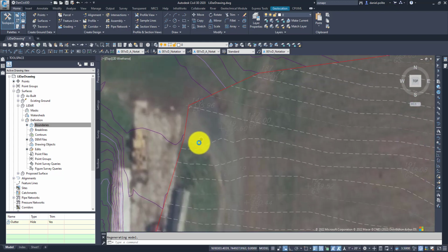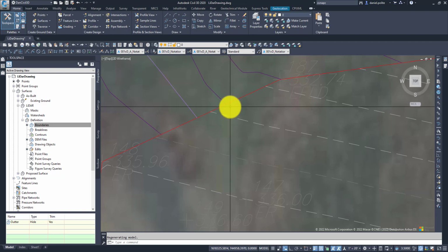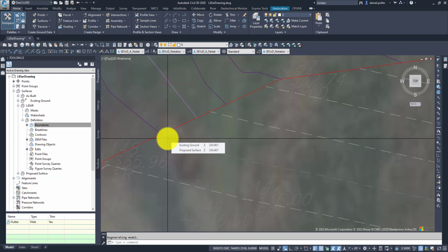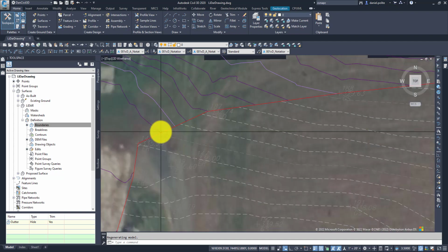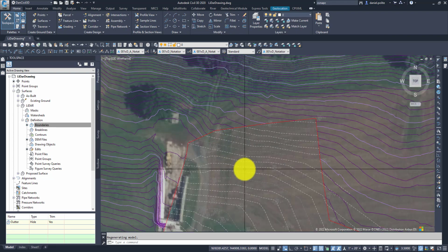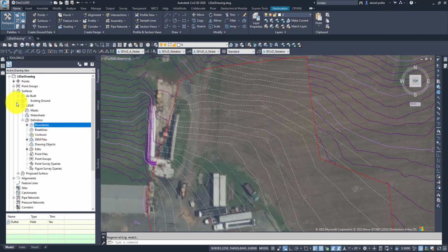Again, this is just coming in contact with, here's an elevation here, for example. This is 333.7. Once we jumped up to the LiDAR, 338.9. It's about 6 foot off. And that's what we're doing in this example. So this is 335. This is 341 approximately. So LiDAR needs to be adjusted down 6 foot to match better with our surveyed surface.